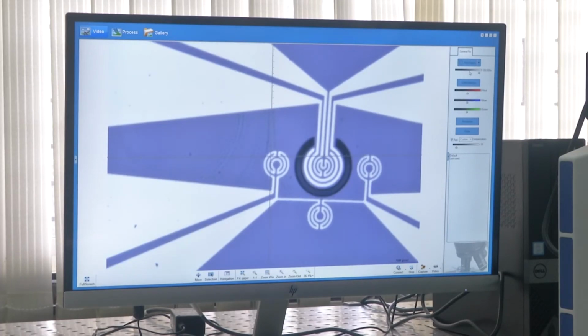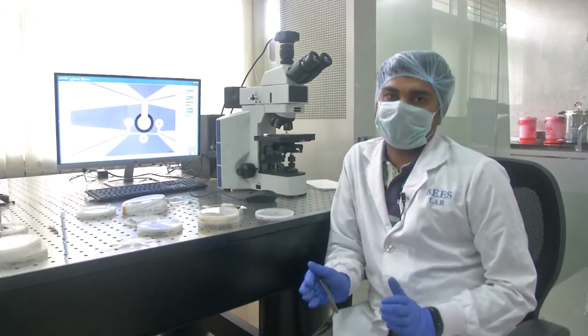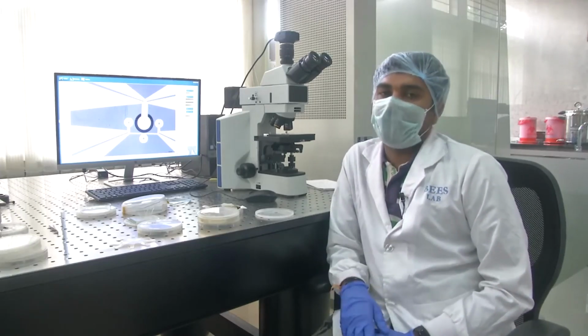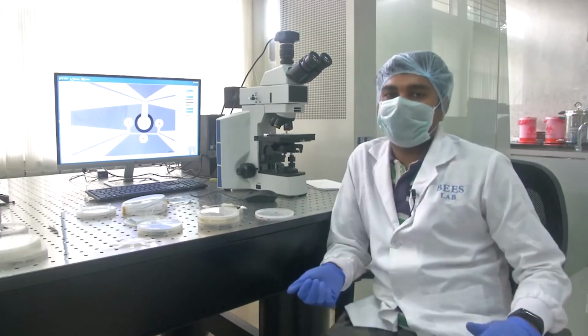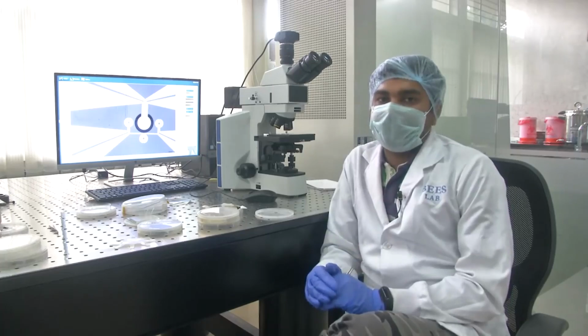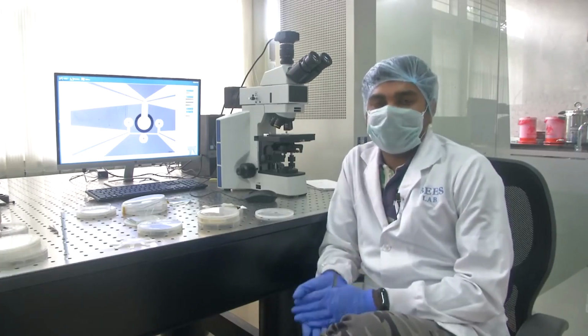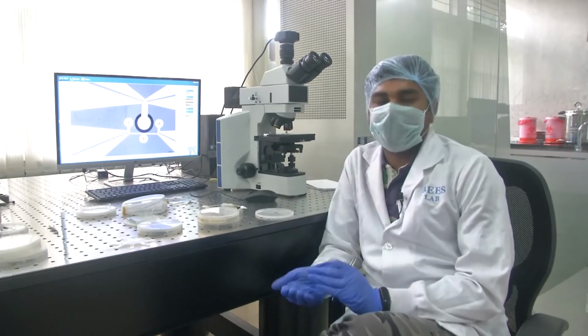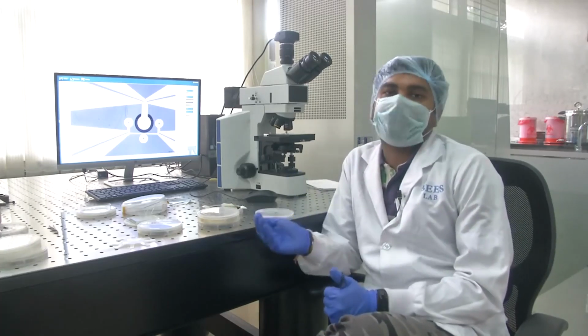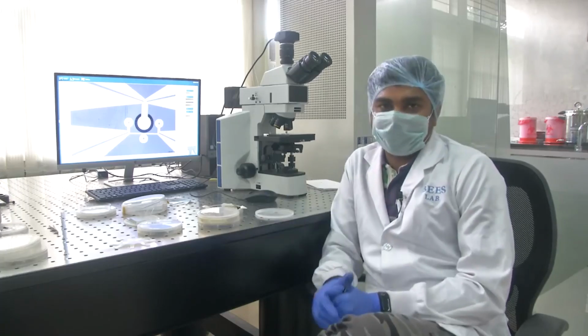So you have seen how the sensor structure is. So let's come back. We have seen how a silicon wafer, which is 500 micrometers in thickness, can be diced. How platinum material can be deposited on top of the sensor, and how it will be diced, and what is the process that you use if you have a material for which you don't have a proper etchant which can give you controllable etch rates. What is the alternate process that you can go for, which is lift off, that we have seen.